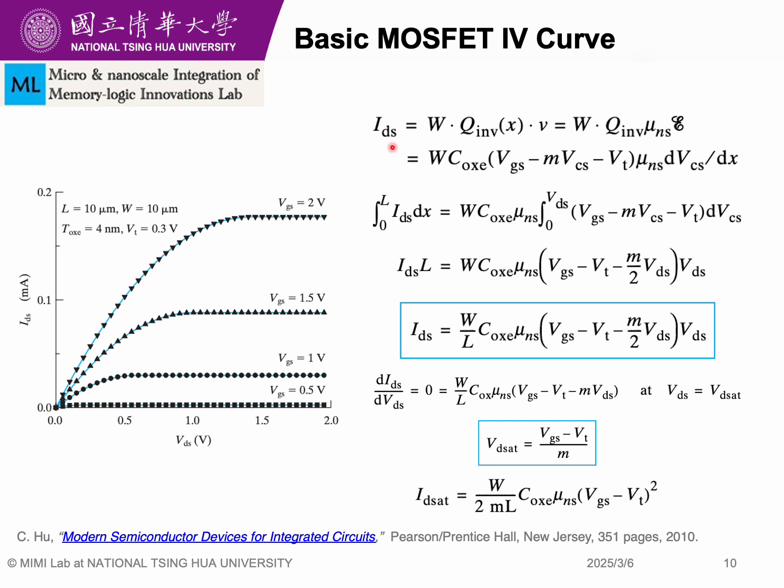This is equivalent to something like a mountain stream feeding into a waterfall, where the flow rate in the stream is determined by the slope of the river bed. The flow rate is IDS, the slope of the river bed is the dEc/dx, and the amount of water in the stream is equal to the inversion charge.